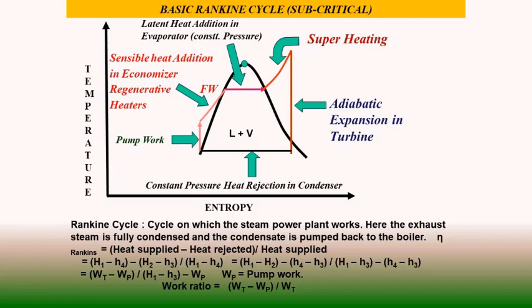Now, whenever we want to increase the specific heat capacity of steam, we can continue to increase the superheat temperature, and we can also increase the pressure. But both these processes have limitations, and due to those limitations we have to see how we can improve further beyond these two enhancements by regenerative feed water heating.